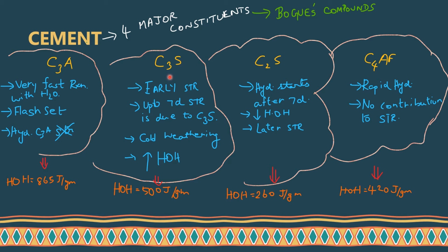And the second parameter is your C3S, nothing but your tricalcium silicate. Here, it contributes to early strength gain. Up to 7 days strength is due to the presence of C3S. It is most probably preferred in cold weather conditions. Here the heat of hydration is high.